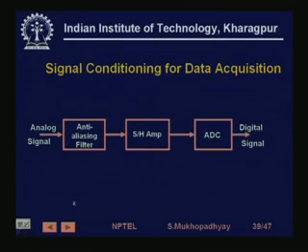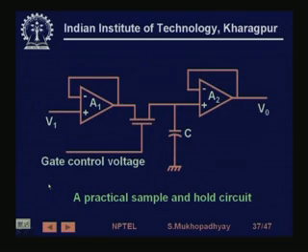And the sample and hold amplifier basically takes certain values of the signal and holds them constant, again takes a value of the signal, again holds it constant. So it samples the signal and then holds it constant in between. So you need to put these three typical blocks: an anti-aliasing filter, followed by a sample and hold amplifier, and then followed by an ADC.